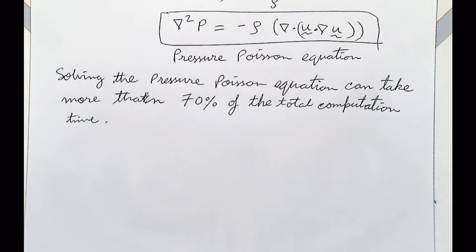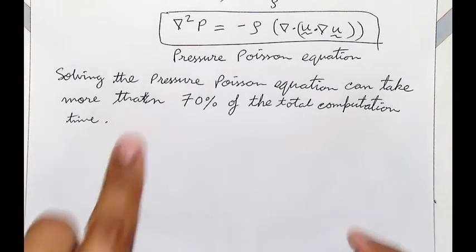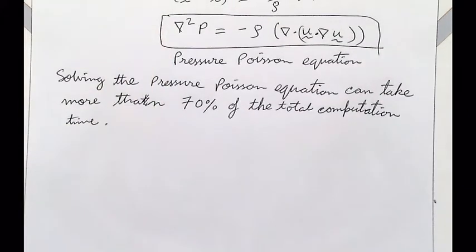So people have come up with many clever ways of doing this. You can use FFTs, fast Fourier transforms, to do this very efficiently. Or you can use another method called FMM, fast multipole method, which solves Poisson equations in general, not just the pressure equation. If you're talking about gravitational forces, you get the same mathematical equation. So people have been working on this for a long time, and you don't have to reinvent the wheel, we can just use what they have come up with.